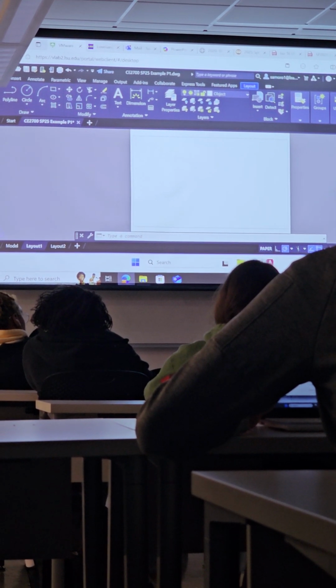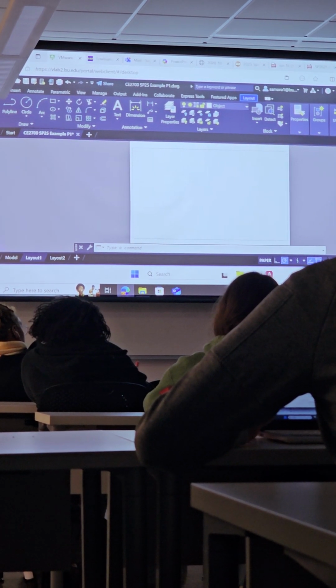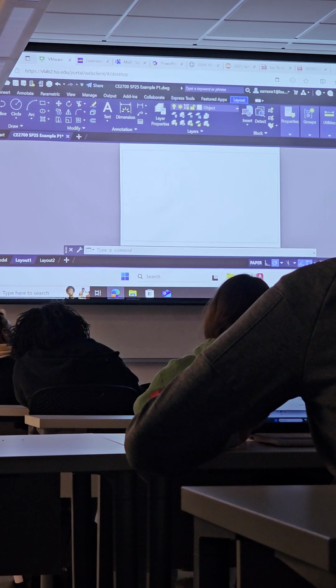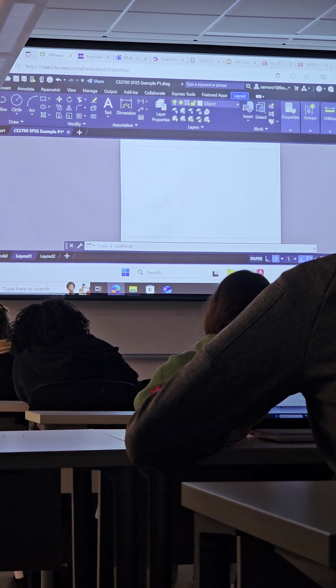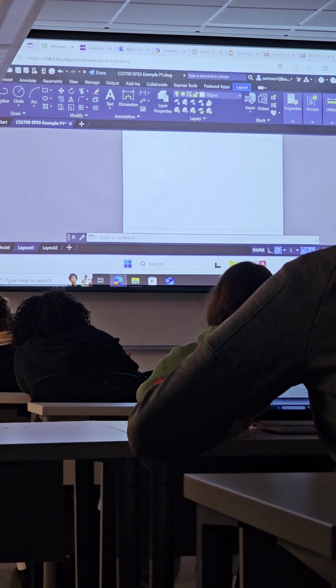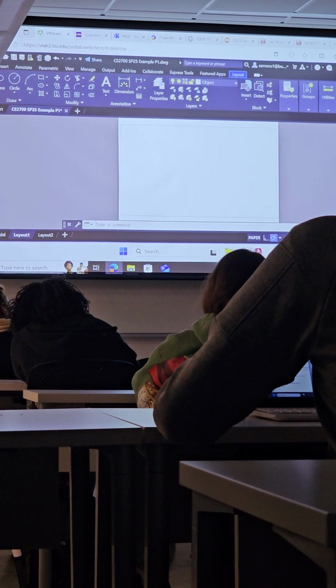You want to draw that title block once. And if you make a change to it, you want that change to propagate and be displayed in every drawing that includes it, right? So using an external reference is the way to do this. Draw the title block once, and then show the contents of that file in every drawing that needs it. So that's what you're going to do.